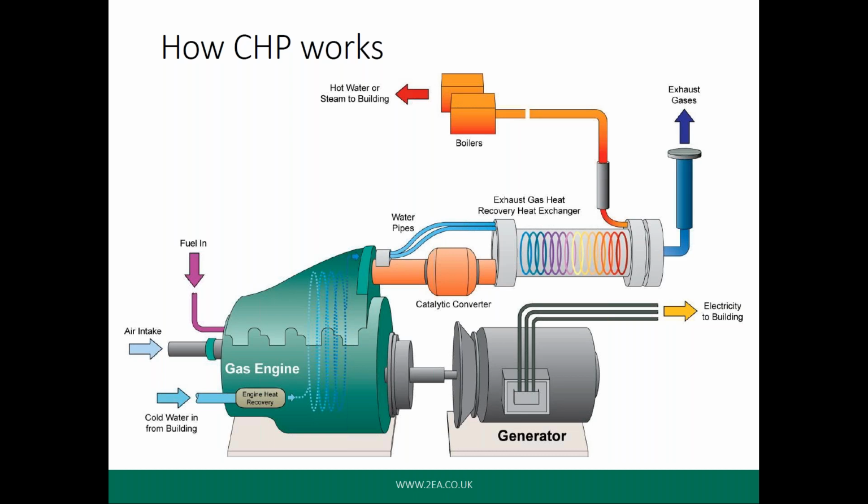It's important to emphasize here that there's no switching involved, unlike with standby diesel generator sets. The cables from the combined heat and power unit are connected in parallel with the incoming power from the utility. The laws of physics mean that the energy generated locally is consumed first, with the utility seamlessly topping up to match the energy required by the site.